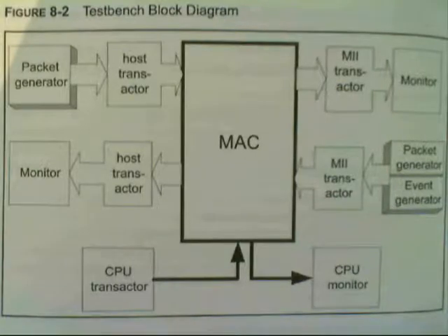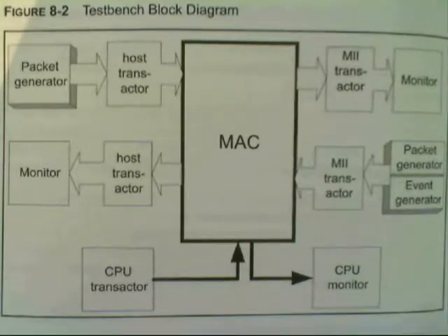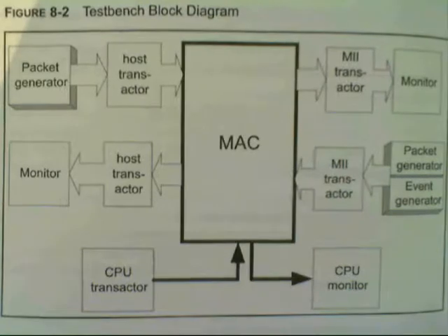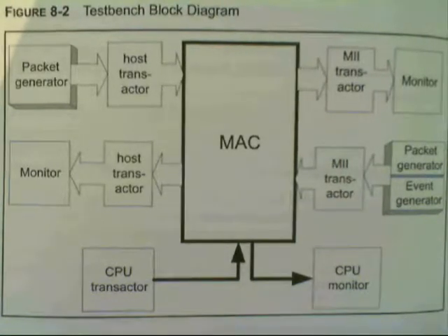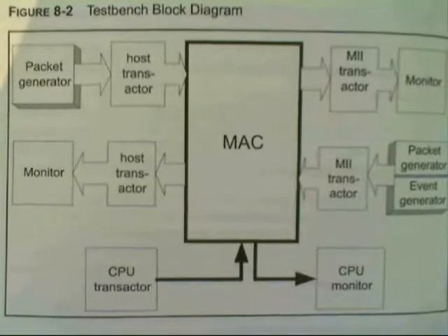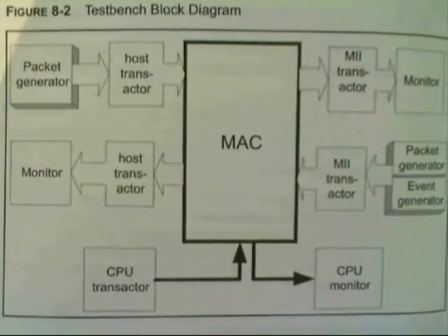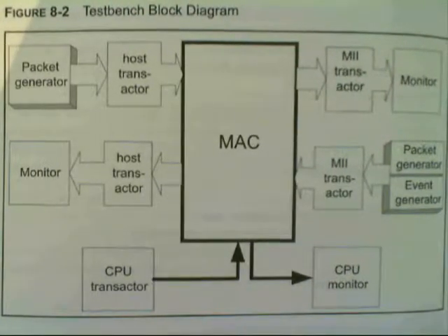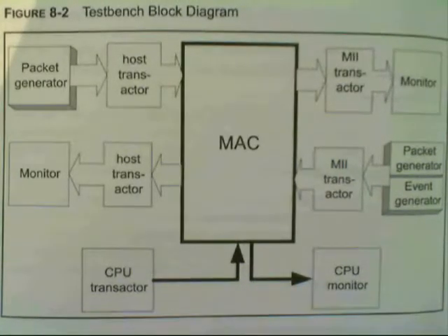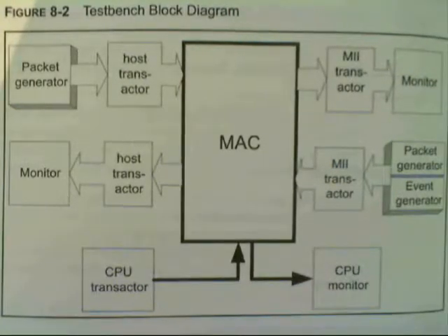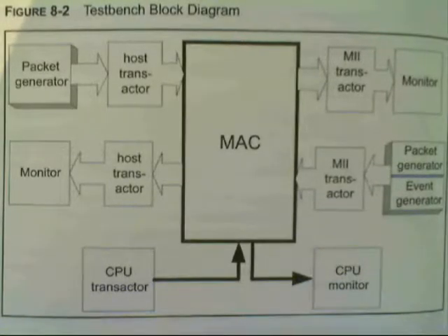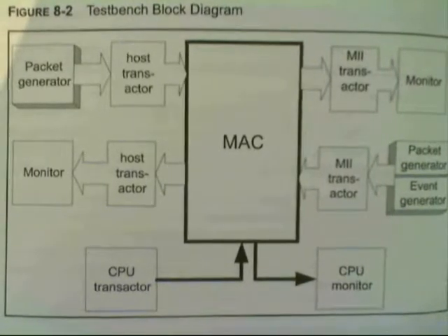Functional verification for the MAC core is performed with an automatic stimulus generation and randomized testing. For stimulus generation for the MAC controller, the test is divided into three categories: normal, transmit, receive with errors. An important element of the MAC verification process is controlling packet distribution, packet size, the MAC destination address, alignment errors, and CRC error packets.